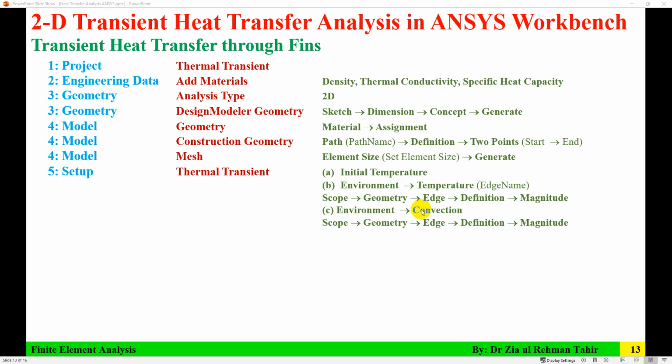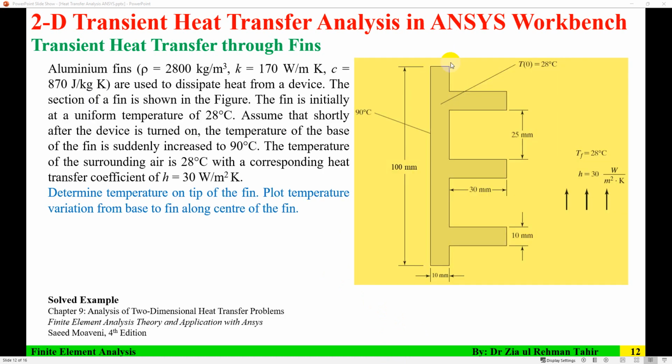Next step in the environment, apply convection and the convection heat transfer coefficient and temperature. So for all other edges, temperature is 28 and heat transfer coefficient is 30.